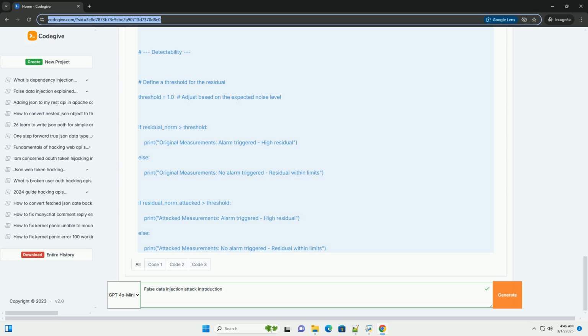3. Calculate the attack vector, a, using the chosen c and the measurement matrix H. The attacker calculates the attack vector, a = H c. 4. Inject the attack: the attacker injects the attack vector a into the sensor readings by modifying the data transmitted from the sensors to the control center. This can be done by compromising RTUs/PLCs, performing man-in-the-middle attacks on the communication network, or exploiting vulnerabilities in the control center software. 4.